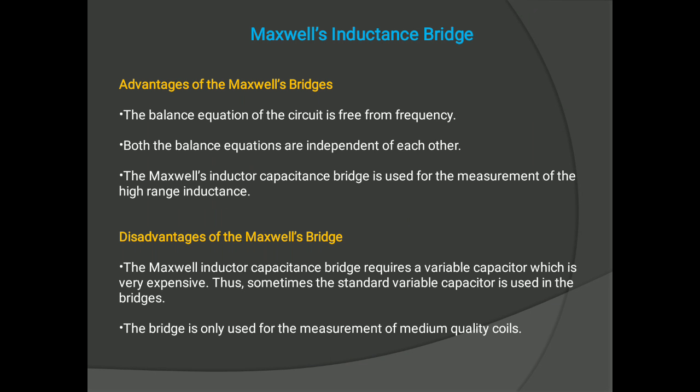Now, advantages of the Maxwell's bridge. The balance equation is independent of losses associated with inductance. The measurement is independent of the excitation frequency. The scale of the resistance can be calibrated to read the inductance directly. A wide range of inductance at power and audio frequencies can be measured.